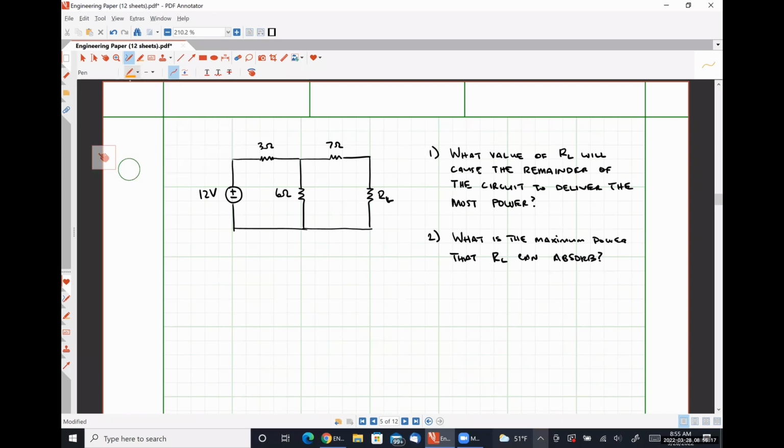So what I'm going to do, I'm going to put a pair of terminals here. I'm going to erase this guy. And I'm going to replace at those terminals with my electrically equivalent source, which was a 3 ohm resistor in parallel with a 4 amp source. Are we all in agreement that that's what our electrically equivalent circuit should look like after this first step here? All right. So what can I do to simplify things now? Seth.